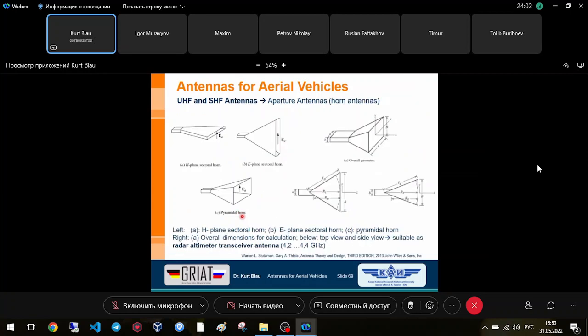And another type of such antennas, not the reflector antenna, is the so-called horn antenna. And I showed you some things here. We have a waveguide as a feed element. All the time we have not discussed, let's say, the basics or the fundamental principles of such a waveguide. It has a completely other radiation and wave transportation mechanism in comparison with a TEM waveguide like a coaxial line or symmetrical line.